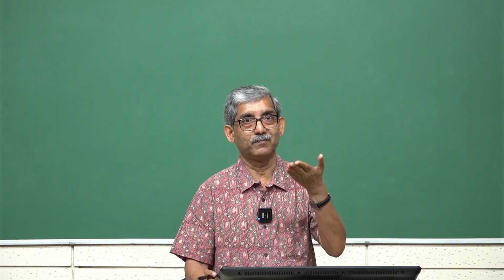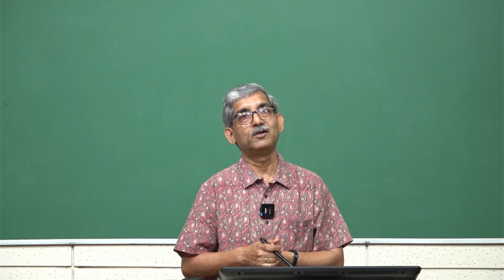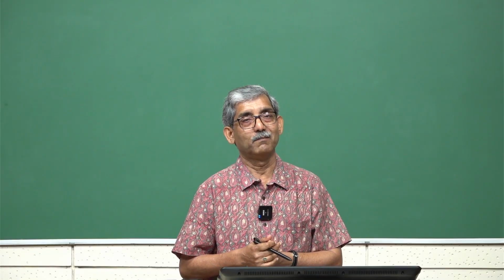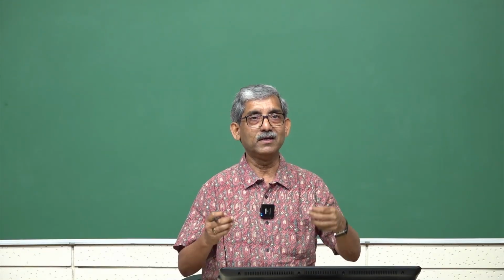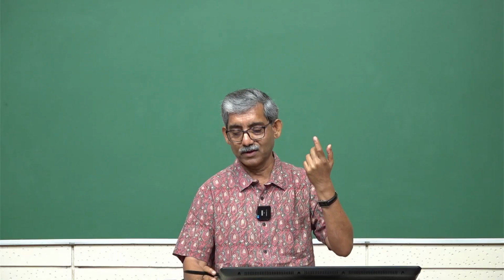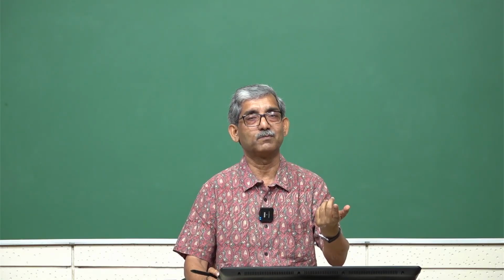Now, twist in the roving. Twist should be as low as possible. Ideally, given an opportunity, if we can handle the roving, it should be 0. Because we cannot handle it, we need a minimum strength, that is why a minimum twist is required.